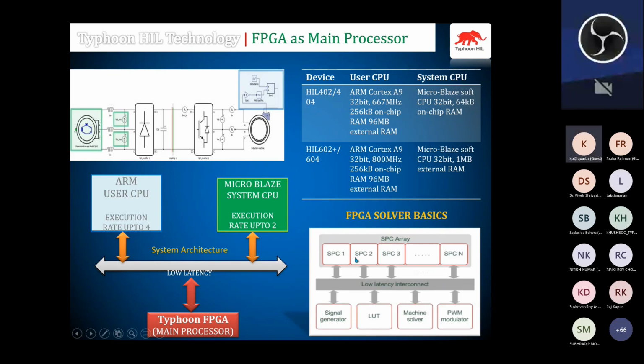It is in charge of simulating electrical circuits that consist of linear passive elements, both constant and time varying, converter blocks consisting of ideal switches, and contactors that are based on ideal and non-ideal switches. So these SPC blocks are interconnected through dedicated communication lines, which allow them to exchange variables with a single simulation time step delay.